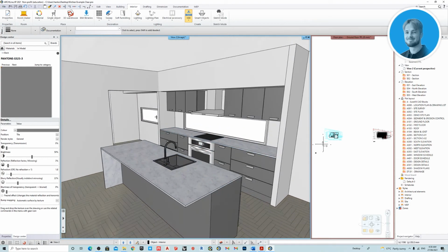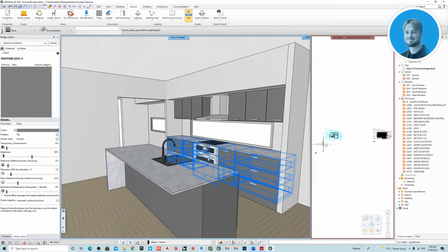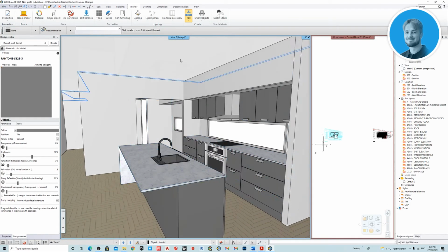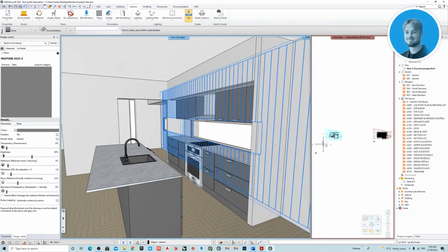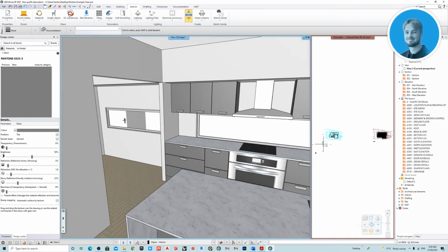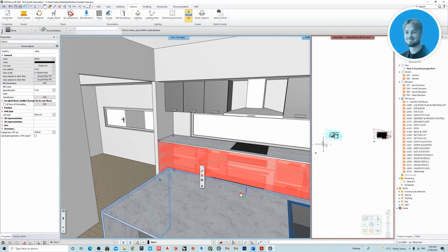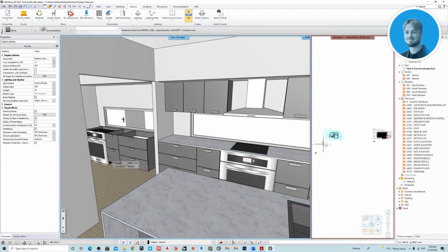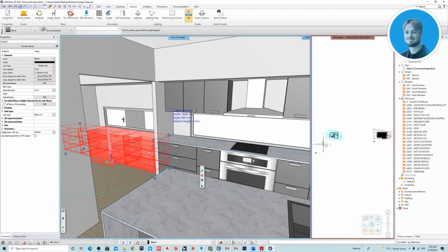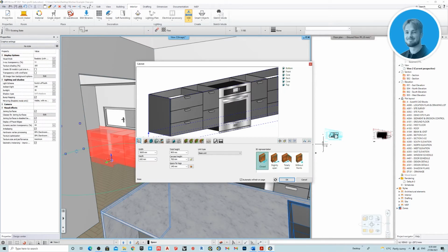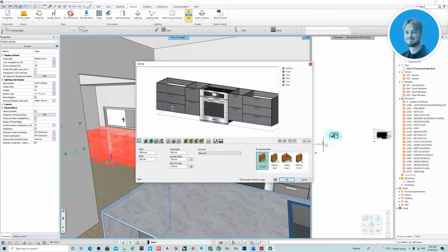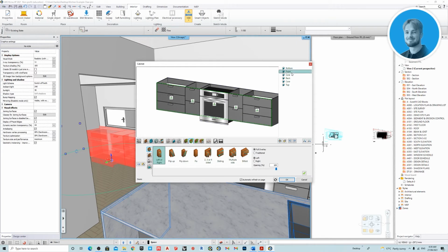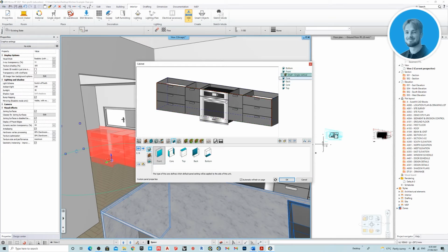Now the next step here is just to do the pantry, and then from that we can start adding some lights, we can start adding some furniture. Okay, so the pantry is very straightforward. So we're going to follow the exact same process. Just going to copy it across. For this one, it will be a different size. So we can just input that and we can just clear the front profile. So let's just remove everything to the front.